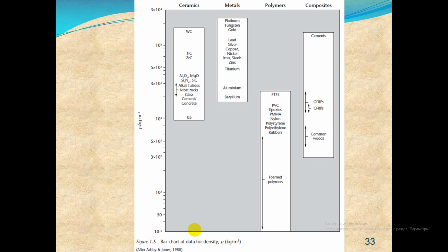And this can pose a serious problem if water has been absorbed into cracks in structures or into individual materials, as frozen water undergoes a 9% volume increase, and this can cause stressing and cracking of those materials which are inherently brittle.